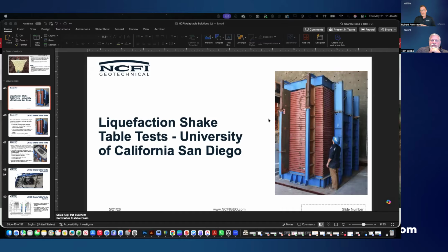The problem you have in that case is if it does expand, it may cause some unneeded lift in regards to the structure that it's supporting. If it's overly saturated, the material is going to spread in a bulbous way and push the soil out, and it's not going to permeate. So we advise, if it's going to be used in an environment with expansion, to utilize it in the in-between stages as far as saturation and expansion are concerned. That's coming from experience that we have, especially from folks in those regions who are continuously dealing with that. But again, from a chemical standpoint, it's not going to augment it.